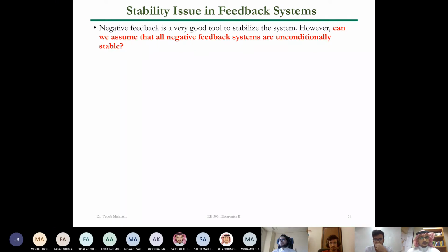I don't think it's true. Not true. Why do you expect it's not true? It's not necessarily always going to be stable. Okay. Always. Okay, so what do we know about the pole? If you have a pole in a system, what is the phase introduced by that pole? I mean, usually, it will introduce a phase shift of how much? Each pole? Minus 90. Minus 90, exactly.